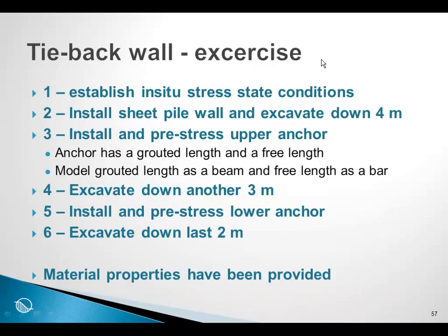So the exercise is to establish the in situ stress state, and then to install the sheet pile wall and excavate down 4 meters. Then once that's been done, then to simulate the installation and pre-stressing of the upper anchor, and we will simulate the anchor as having a grouted length, which will be a beam, and a free length, which will be a bar.